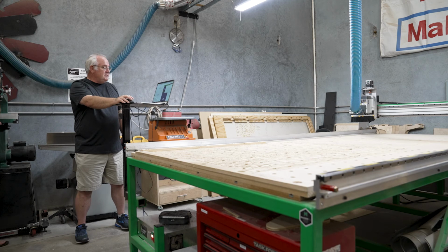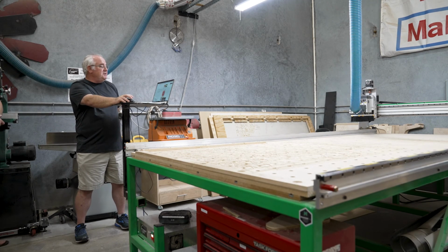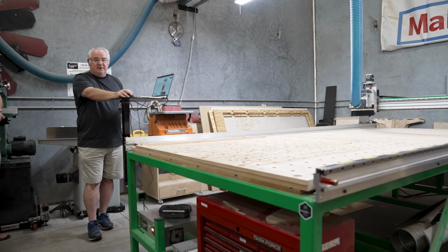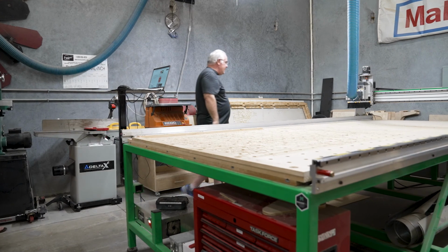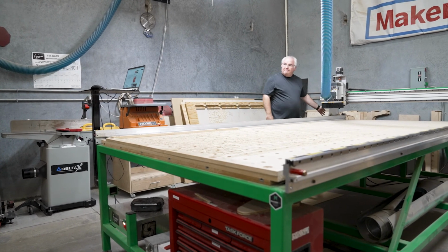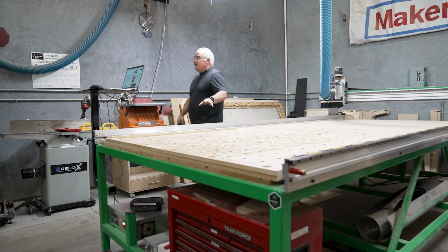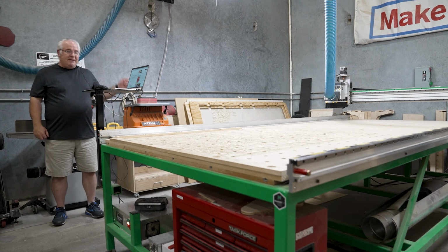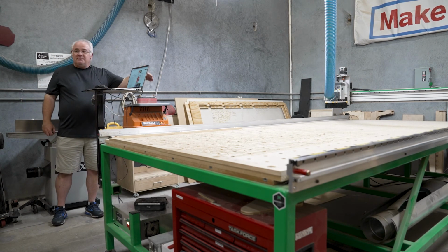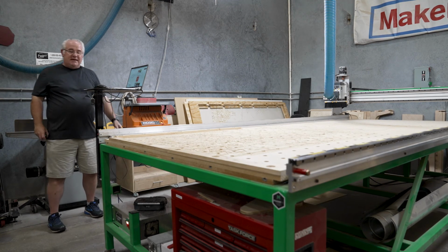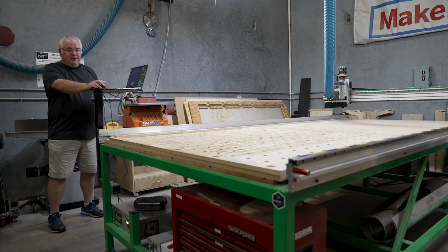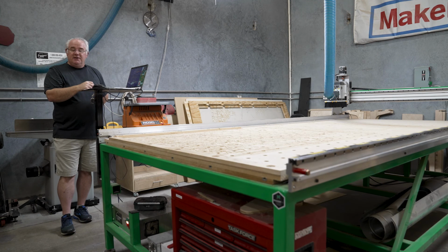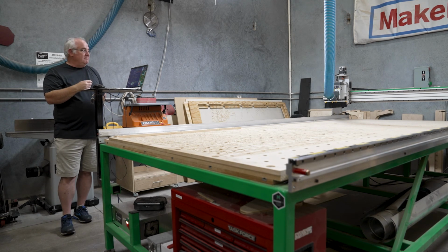So you just follow along. It talks about the 2 applications. The first thing to do is to verify that the gantry is in the home position. So the gantry is down here that holds the spindle, and this is the home position. The last thing that we do is we initiate a park command that will actually park the machine in that position. If you happen to find somebody didn't do that, you would first have to manually jog the machine back to close to that location. You would have it powered up, and you would use the green application to actually move it. Okay, so don't ever manually try to move the gantry.